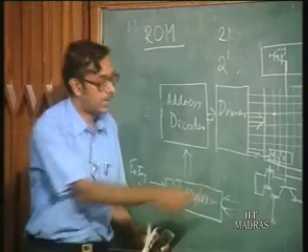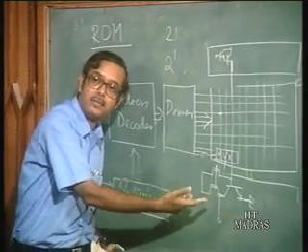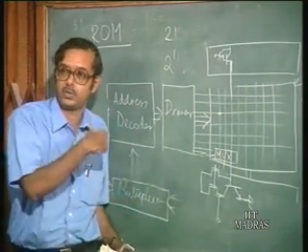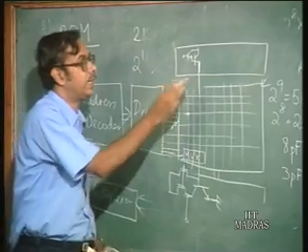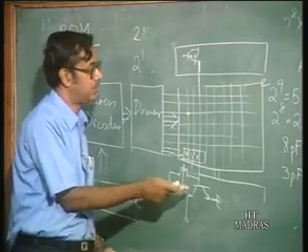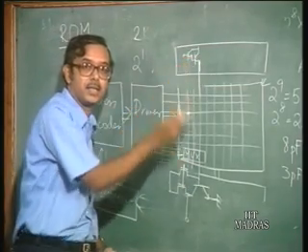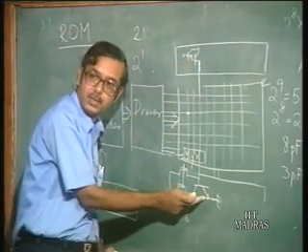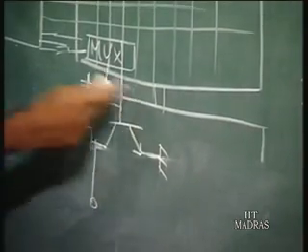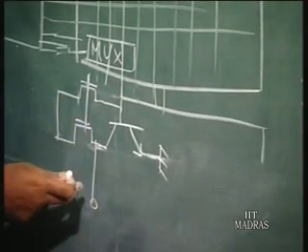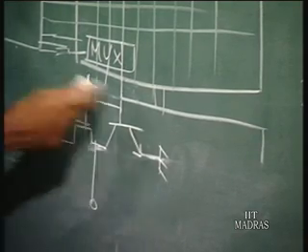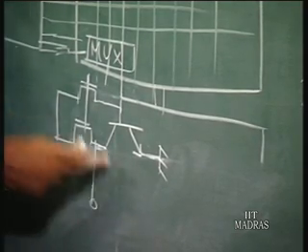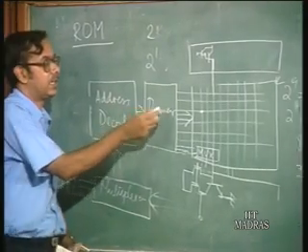Whereas the output voltage here can go all the way from almost 0 to 5 volts. So, there is no problem. And here the bipolar transistors are used for pre-charging and also at this output here. So, this is just like a BJT inverter, the bipolar inverter here. All right. So, we have used a bipolar inverter here, as well as in the driver circuit.